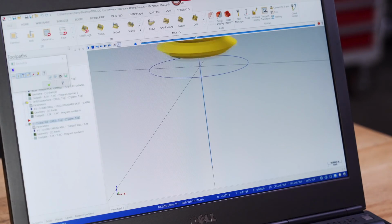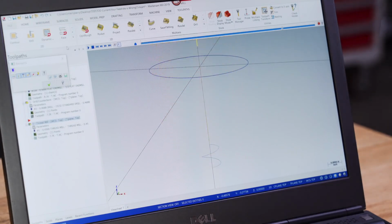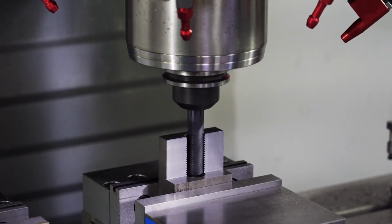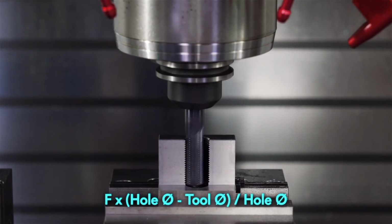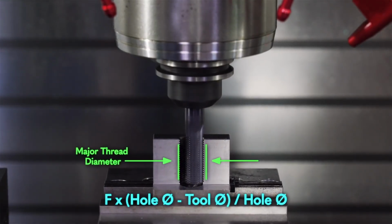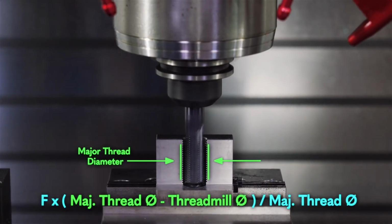We'll see this type of feed rate error all the time when thread milling. When posting our programs from a cam system, our thread mill is moving much faster at the edge of the tool than it is at the center of the tool. Now we can use the same formula to adjust our feed rate for thread milling. We just replace our hole diameter with our major thread diameter.